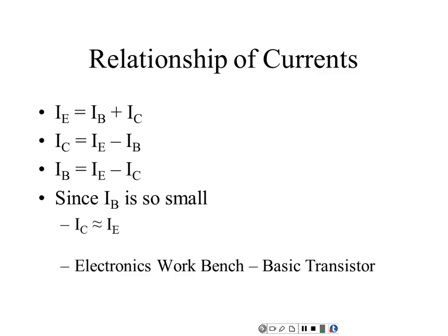Well, if you knew the transistor and you knew how it operated, then you wouldn't need this formula. And of course, for calculations later on, we're going to say that IC is what? You know what the little squiggly line means? Roughly or approximately. Good. It's not equal to it, but when I get into calculations, we've got so many other approximations going on that a lot of times we can use this formula. So if I say IC is equal to IE, true or false? That's going to be false, right? If I say IC is approximately equal to IE, that statement would be true. So watch for that on the test.